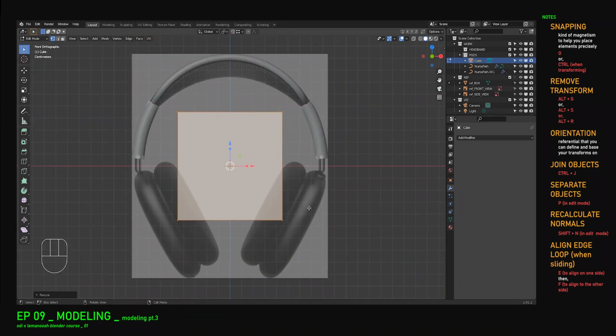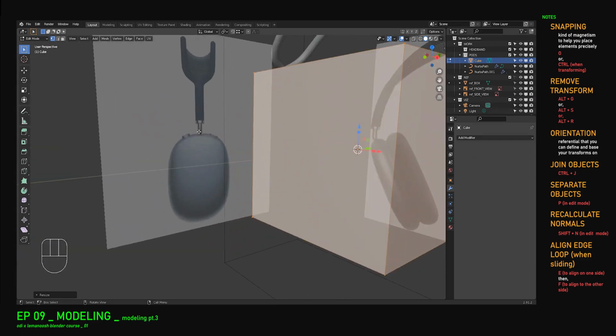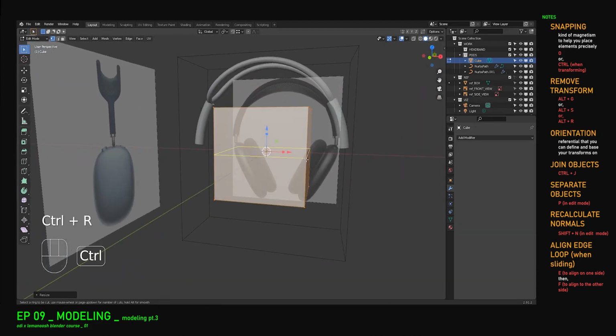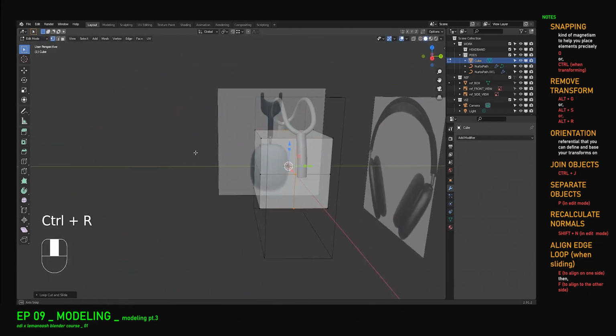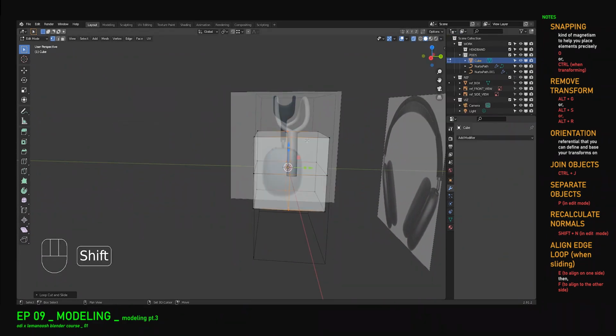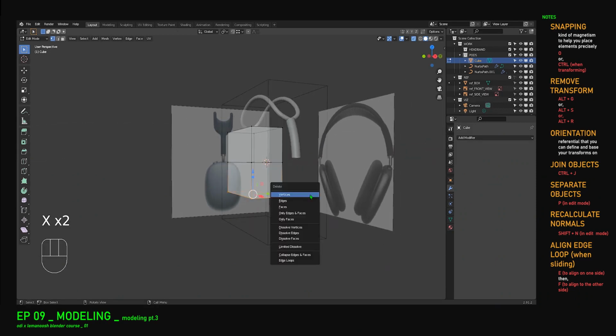So we can see that it's symmetry in both axes. So we can just do 1/4 of the pod, and it will just be mirrored in this direction and this direction. So it means that we can cut the cube here and here. And now let's activate X-ray. Now you can delete all of these points and all of these.